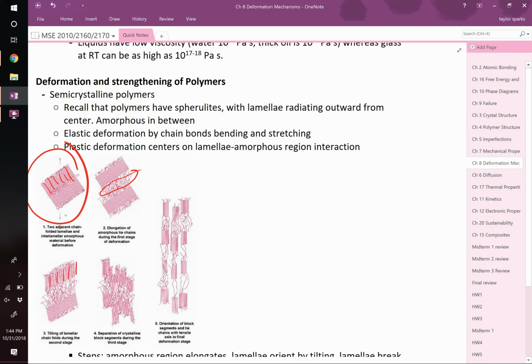So ropes, right? This wouldn't be a good climbing rope, because with this, you've generated a lot of strength at the expense of all of its ductility. So for a climbing rope, you'd actually want something at neither end, remember. You'd want strength, so maybe part of the way here, but you want some of this amorphous region to be elastic, right? You want to have some ability for this thing to stretch without breaking.